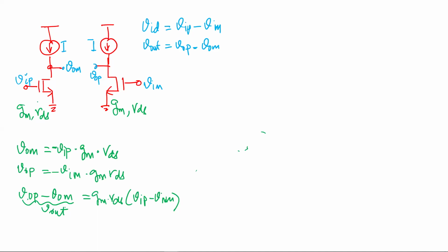But obviously if you want high speed circuits, then you have to increase the gain in some other way. So you get the differential gain, right? So this is the differential gain, which is AD, correct? This is AD, and we can design circuits to make this AD high. So that's one condition which is met for us.